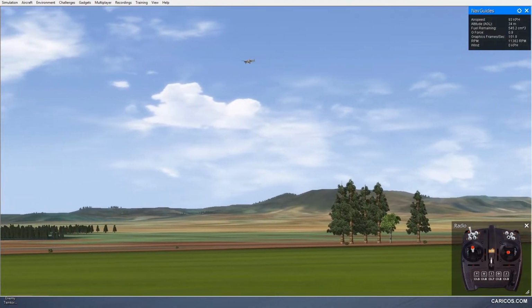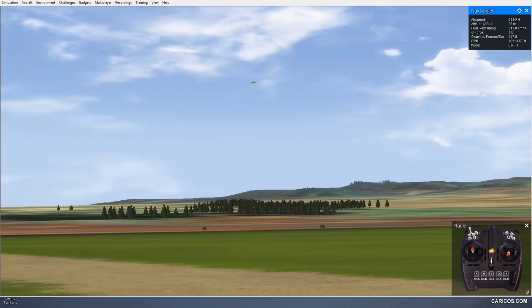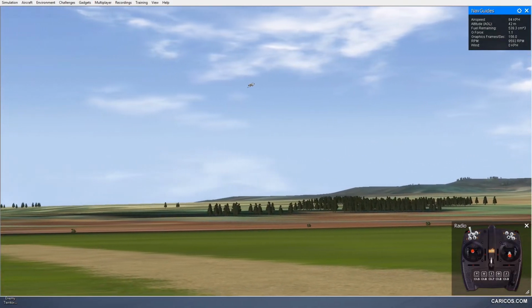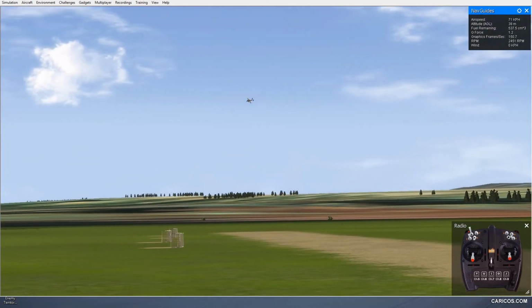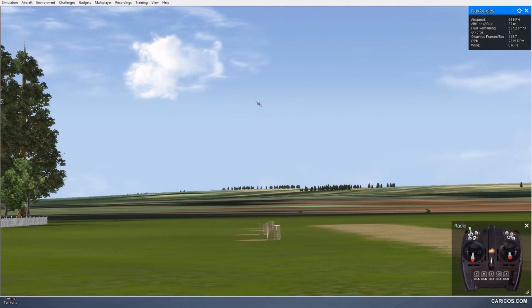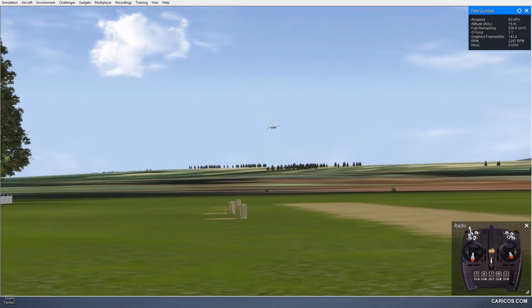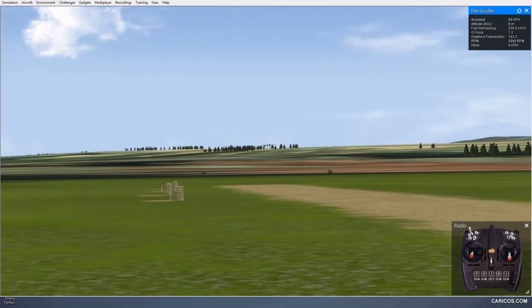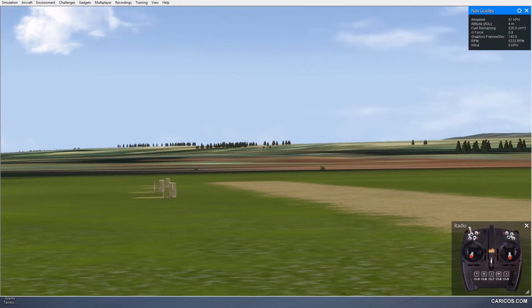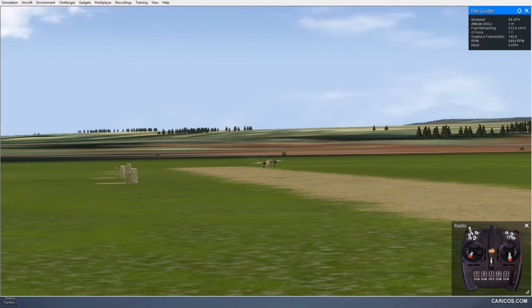So here's the downwind leg that we're doing right now. Once you get a decent distance out, you don't want to overshoot. A lot of times you overshoot this and you end up too far. I'm pulling in some of the landing flaps right now, so now I'm just adjusting. I got it all the way down to idle, and I'm going to come in for the landing. All I want to do is start to add a little bit of power as I'm slowing my descent rate here. I'm adding power, adding power, and I want to barely just touch the surface here.